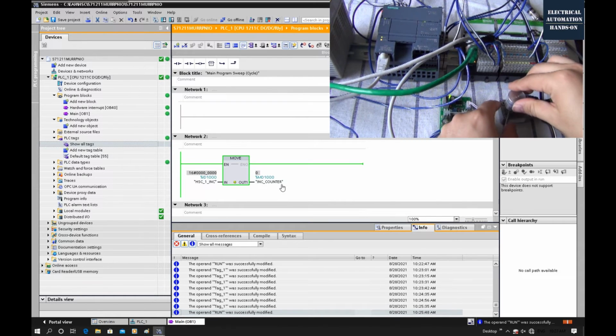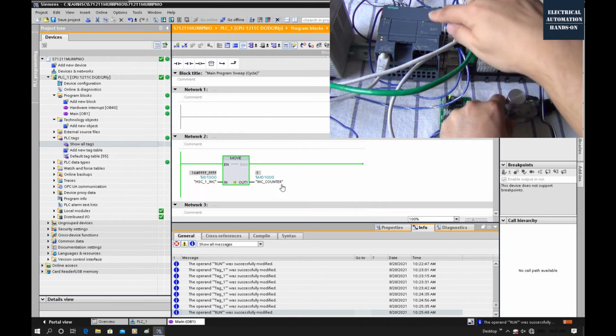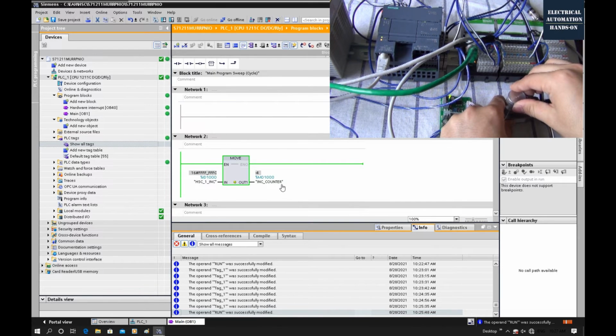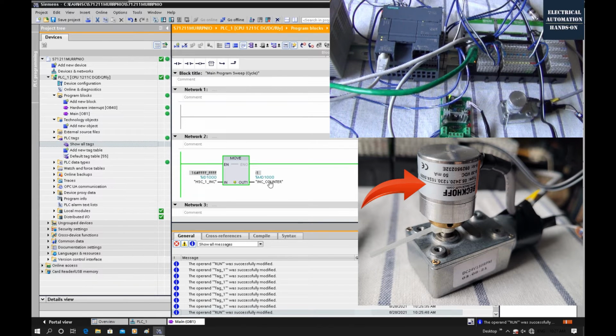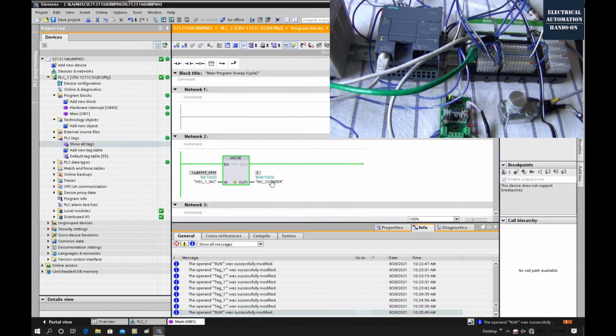And now if I spin this motor, we can see these 2 channels are flashing, which means it's reading something there. Okay. And in the meantime we can see this channel value is changing. My incremental encoder is 1024 lines per revolution. So now if I spin this motor, we can see the counter value from this channel. I will run the motor roughly around 1 revolution per second. Okay, so now I will start this motor.